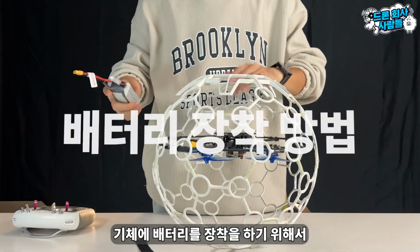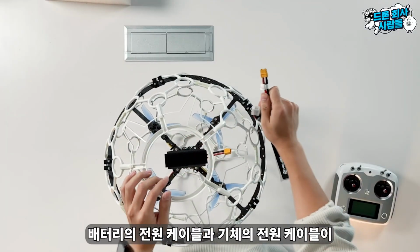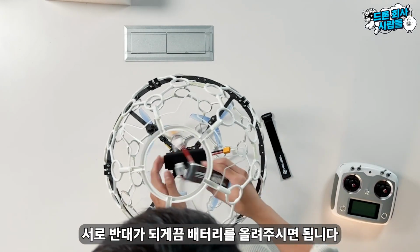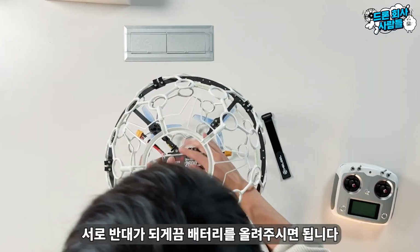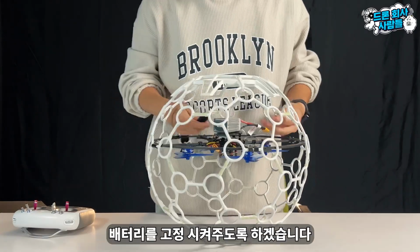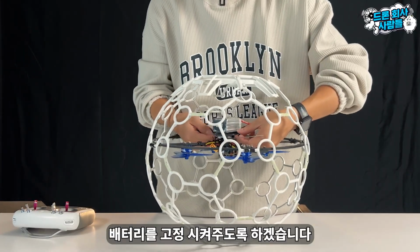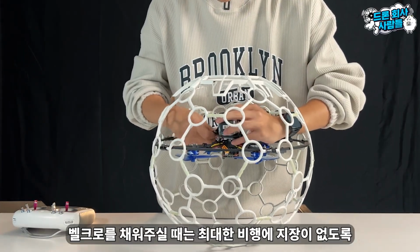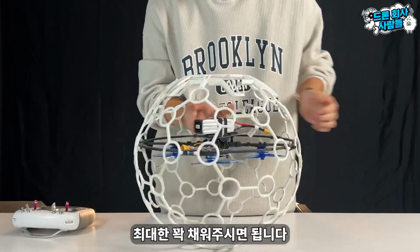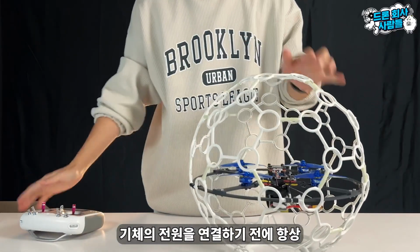Now, to attach the battery to the aircraft, place the battery so that the power cable of the battery and the power cable connected to the aircraft are opposite each other. Then use the included Velcro to secure the battery. When fastening the Velcro, make sure to secure it as tightly as possible so it doesn't interfere with the flight.